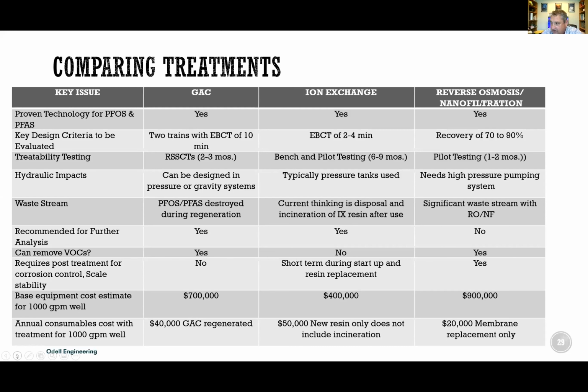The capital costs aren't terrible for PFAS removal, but there's a lot of operational costs, and GAC takes a lot of empty bed contact time, typically have a lead lag arrangement with contact times of around 10 minutes in each of the lead and lag vessels. And with GAC media in the vessels, the replacement cost isn't too bad. But it's important to know how long and how frequently you're going to have to replace them.